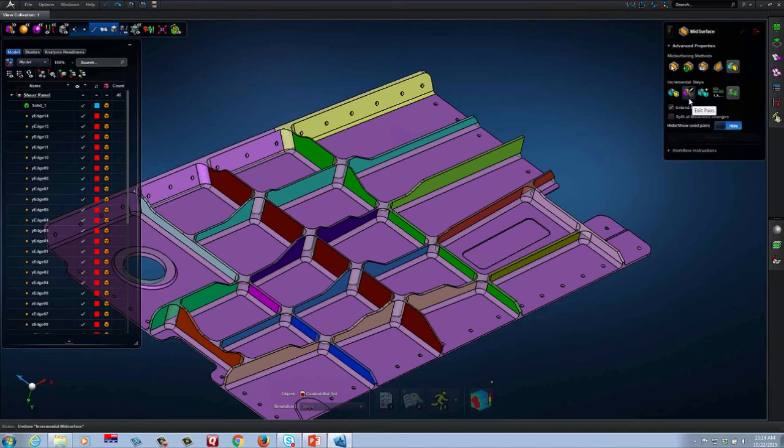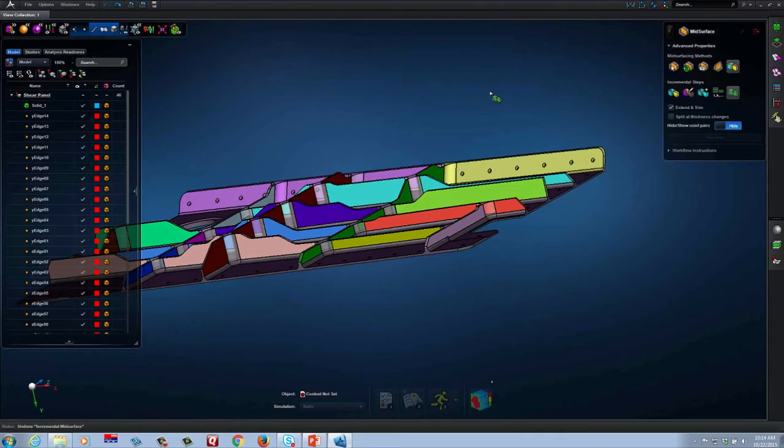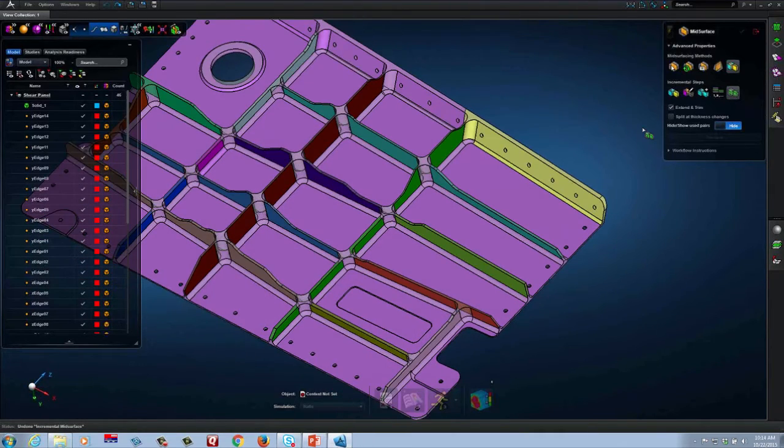Now, the incremental modeling tool provides you with 3 tools that will help you guide the process. One is a tool to edit face pairs where you can add and remove faces. One is where you can merge pairs together. We'll see how both of these tools work. And then another one is an offset tool. In other words, is this mid-surface right down the middle, or is it offset from the left or the right-hand side? Okay. So let's first look at this area where we were missing a mid-surface, okay?